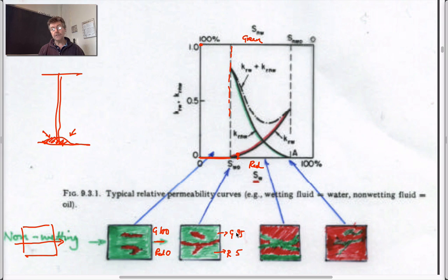The dominant one is because of the cross-sectional area that's wetted. Because there's more saturation of the green fluid, it will make more green fluid. In this case, the higher saturation is red fluid. Remember, we said that we could draw this diagram for relative permeabilities almost like this, just based on the saturations versus relative permeabilities.